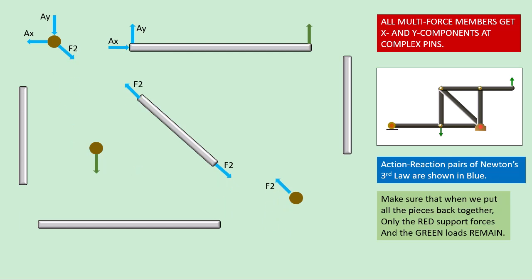Two-force member, two-force member. This is a multi-force member, Cx, Cy, we flip directions. By is the force from the roller support. Dx, Dy is force from this multi-force member on the complex pin.